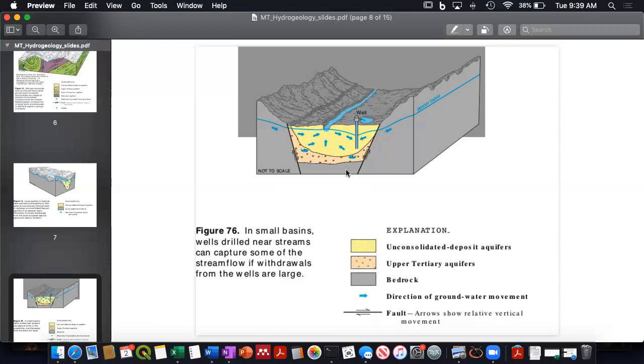Then you need to have what I call hydrogeologic framework. So what are the principal aquifers and their type, what are their relative sizes and their interactions with surface water bodies. So hydrogeologic framework is essentially going to be principal aquifers and types that you think might be there and their general behavior.